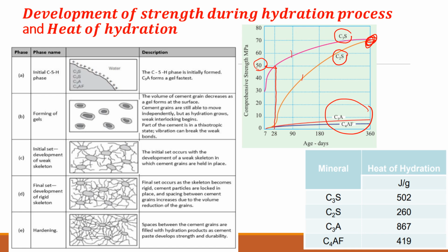And also, if you have a very complicated formwork, you need time to pour the concrete into that unusual shape, isn't it? Likewise, if you are working in a hot summer day, you need time for mixing, pouring, vibrating, compaction. So in a hot summer day also, we need to delay.